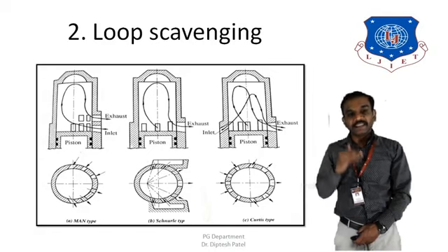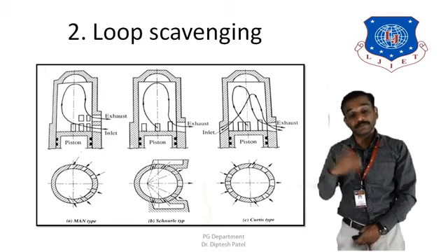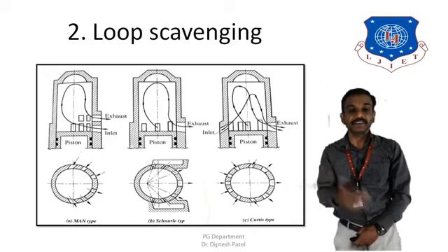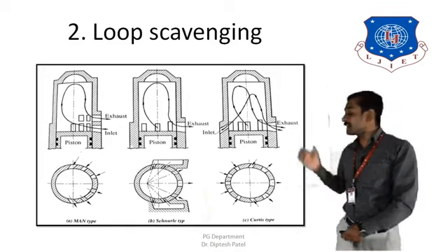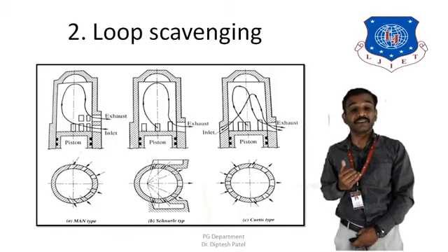And then, when the piston moves from bottom dead center to top dead center, first of all the inlet valve closes, and afterward the exhaust valve closes. So in that kind of system, there is less chance of the loss of fresh charge.